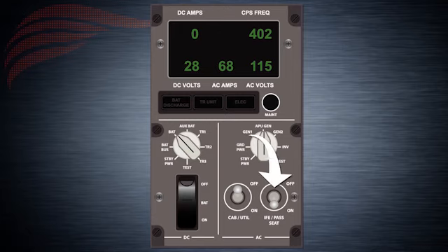Just keep in mind that certain passenger cabin and galley systems are lost when the cabin utility switch is placed off. The in-flight entertainment and passenger services switch works with a similar logic, where if the switch is placed off, electrical power to components in the passenger seats and in-flight entertainment systems is removed. Of course, the only purpose of turning both these switches off would be to conserve electrical power in case there was a shortage or unavailability. If the electricity demand is too high, these switches may also be turned off to conserve electrical power for essential aircraft items.